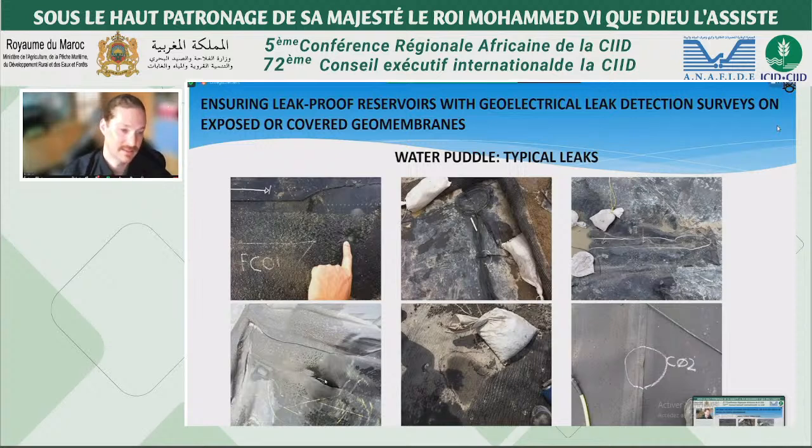And the seam was open because I think there was a lot of tension in the geomembrane, and while the machine was welding, it really warms up the geomembrane, so it was pretty soft at that place, and the seam just cracked open. But the air canal test was impervious inside, so the air test canal was saying it's a good seam, and it was open on the side.